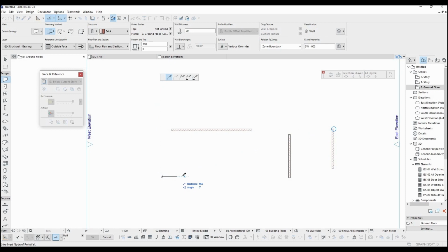You can also lock onto any custom line with the Shift button. As you can see, I first click the starting point. After that, I move the pen over this area. As you can see, a blue line appears. While the pen is on that line, I am pressing the Shift.